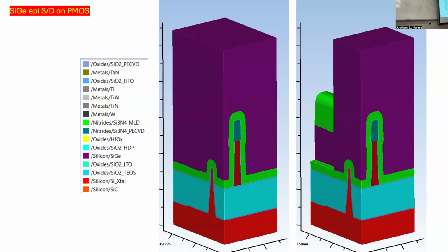That's the main point. So after we grow our silicon germanium, we cover the left side, then we're going to open up our right side. Yeah. And the reason this nitride is there is because you have to use some inorganic material to mask it. You can't use resist to mask it, okay? Because you can't put resist inside a furnace.